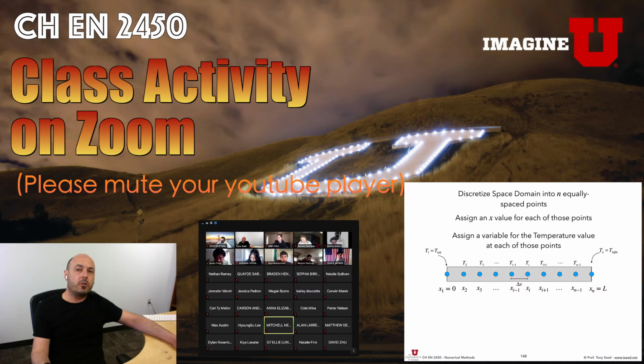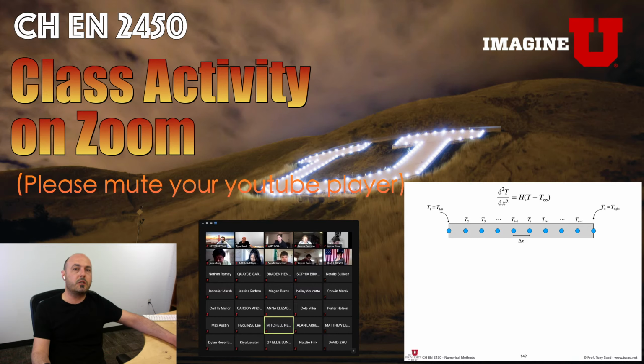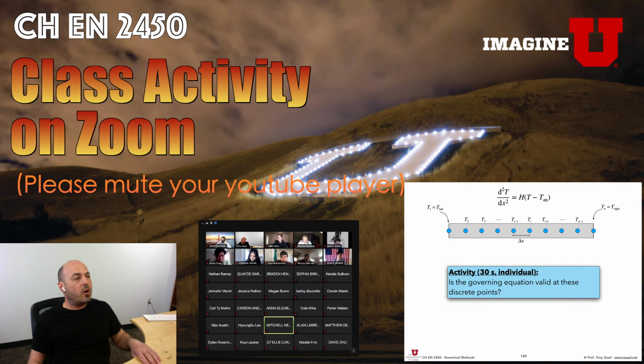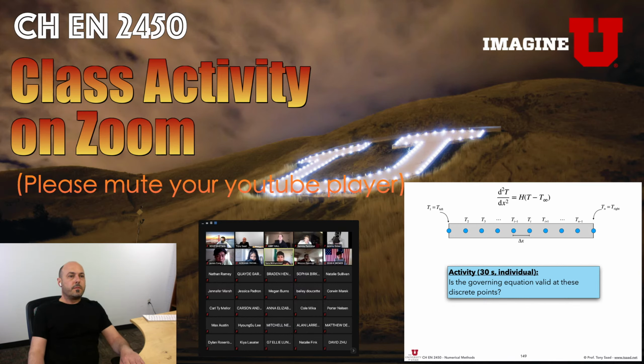Okay, great. Now this is our equation: d2T by dx squared is equal to some coefficient times (T minus T infinity). Now, the second question I have for you is: is the governing equation valid at these discrete points? Simple question. Can I just clarify what the governing equation is? Is it the h times T minus T infinity? Okay, that's only the right-hand side of the equation. That's one term in the equation. The equation, Sarah, is the full ODE: d2T by dx squared equals h(T minus T infinity).